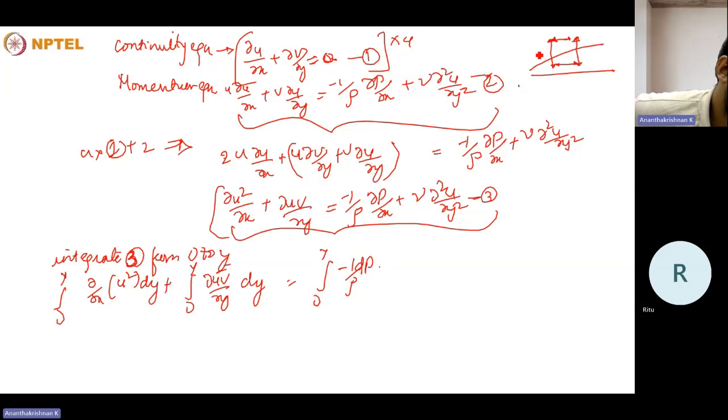Boundary layer theory is applicable when the boundary layer thickness delta is very much less than the plate length L. Using this and the scaling analysis, we could prove that dou P by dou X is very much greater than dou P by dou Y. That means the Y direction pressure gradient across the boundary layer will be 0, corresponding to only a pressure gradient in the X direction.